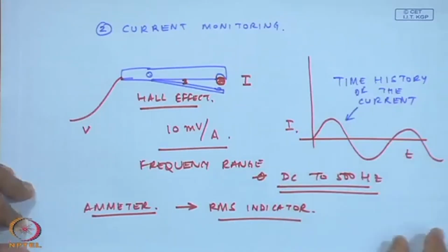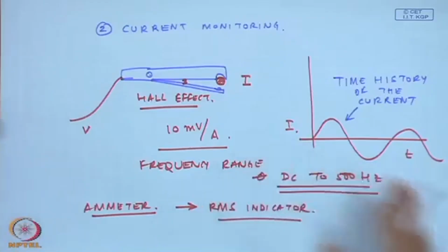Okay, once I get the time history of this current, the entire waveform is available with me. So, with a signal analysis system, I can do the current spectrum analysis and then try to know whether sidebands are there, whether sidebands are not there, and so on. So, this becomes a very convenient way to measure the condition of the electrical motor rather than doing a vibration monitoring.